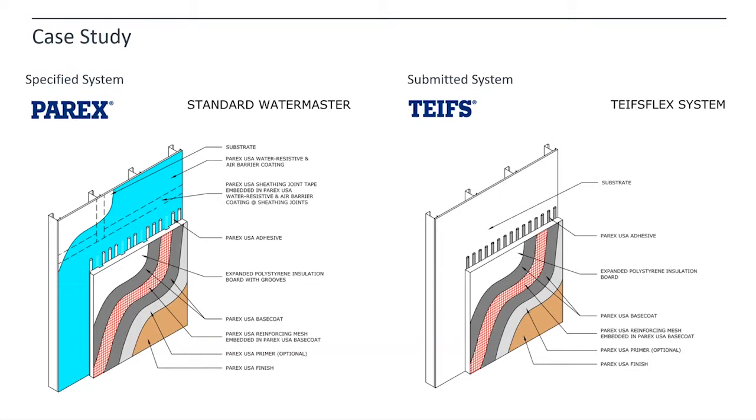So even at the bottom, there's usually an extrusion at the bottom, right? There is, but in this standard buildup between the two, if you were to just discount that they're missing the air and water barrier product on the substrate, and you saw the vertical ribbons, would you think that it had a drainage plane? Well, yes, but if it doesn't exit anywhere, it's useless.